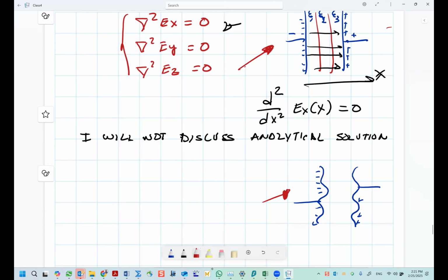So using analytical solutions to validate your finite element solutions is a very good idea. So first use your finite elements to solve this. And if it matches well with the analytical solution, then you go and solve this. If not, I wouldn't believe your finite element solutions. I would probably think that you have a problem.